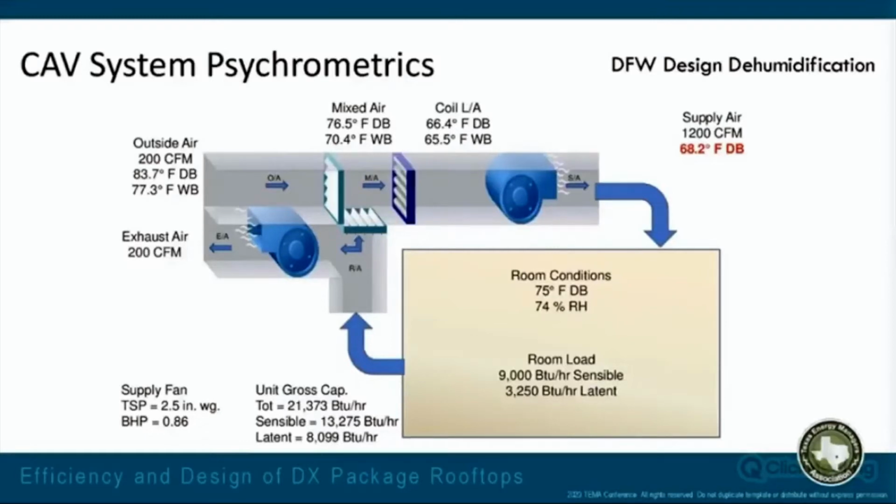Now I made some assumptions on this, and I decided that when you take out all the solar load and you drop the outside air temperature, so you lose a lot of your transmission loss through the walls on an exterior wall, it would drop the sensible load by about half. On your building, it may be something different, but this is what we're going to use for the rest of the day as we discuss the psychrometrics of this system.